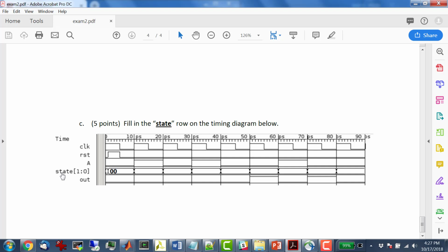Most people use a timing diagram because the time is consistent here, whereas over here, generally a listing will just show you when things change. So in other words, the flow of time is not necessarily constant as you go from top to bottom, but over here it is because there's a fixed axis for time. You guys with me? But in this case, the only thing that's changing is the clock. Everything just changes once per clock, so it's convenient to show it as a table.